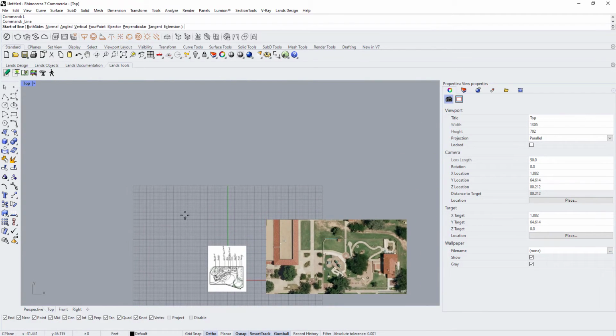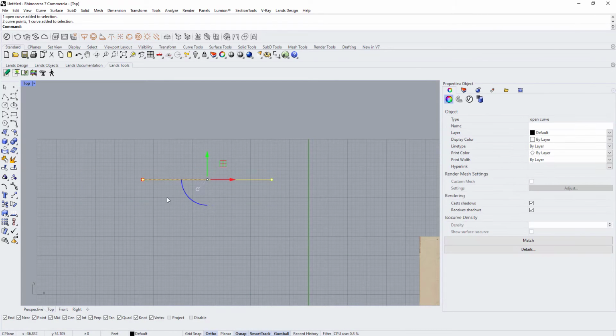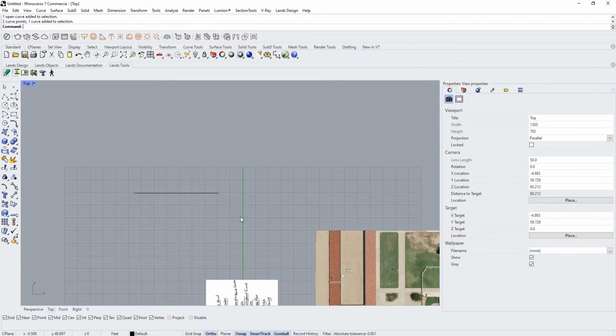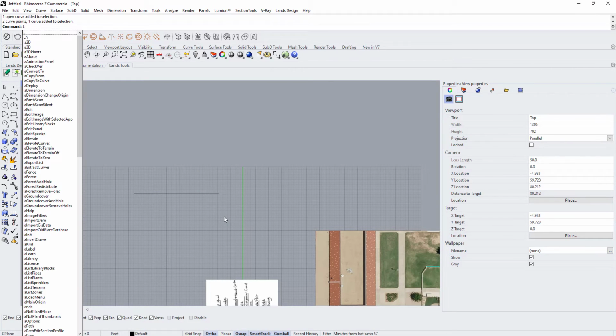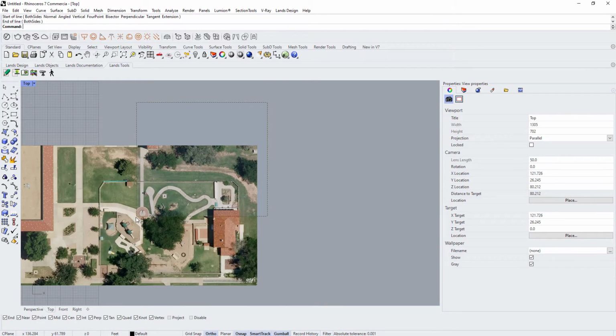I'll draw a line that will be 33.28 feet and press enter and click. So that will end a line at exact 33.28 feet. But if it was meters, all I'd have to do is line and then 33.28, and instead of feet I'll just press M for meters and it will draw a 33.28 meters line. But I won't do that now because I already have the feet.